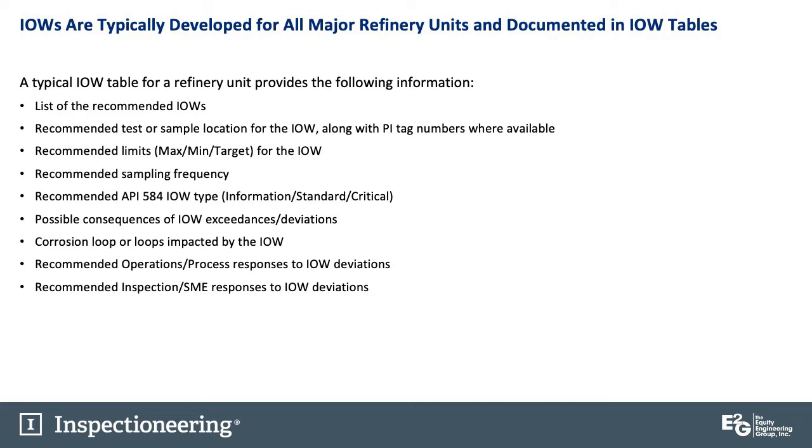So what's going to happen? Like that young FCC process engineer I talked about, when he was having the catalyst carryover into the fractionator, was not well apprised of the possibility that could lead to rapid erosion damage in that fractionator bottoms piping. But if it's documented on these IOW tables, he's got that information in there.